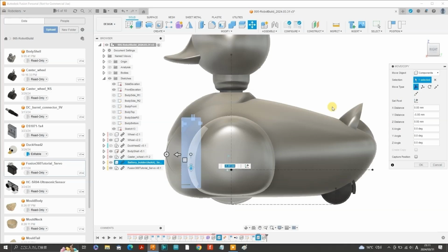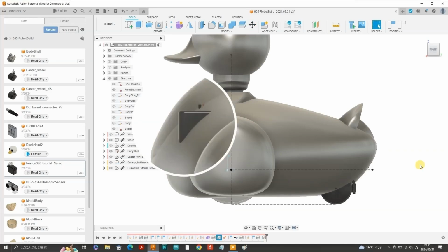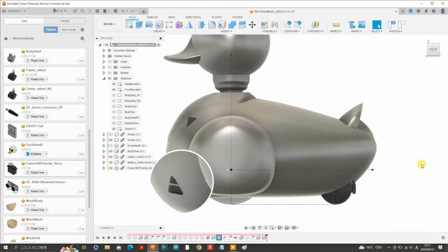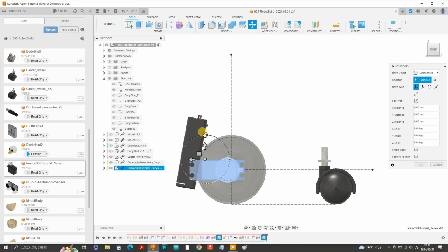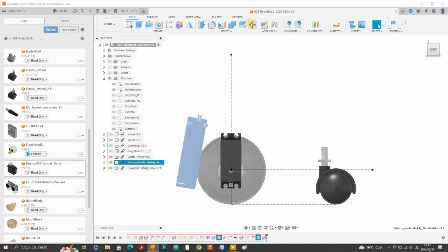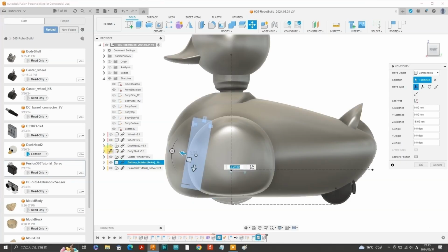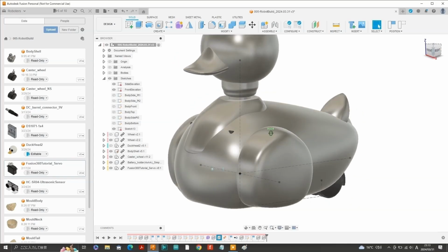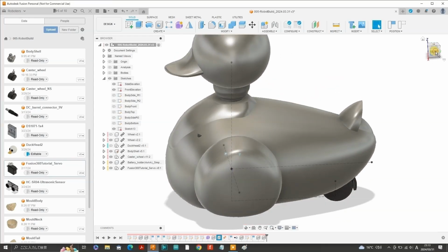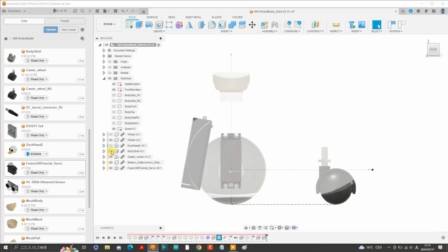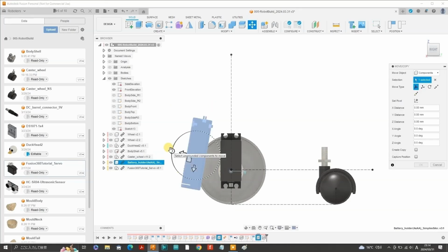If I place the battery holder at an approximately vertical position at the front here, the corners will interfere with the front body shell. So I tried a vertical position for the servo to allow the battery holder to move back more, but 2 of the corners still easily interfere with the body shell here. Also, we'll need to allow for the removal of the battery holder for changing the battery. So I don't think I'll be keeping the battery holder at this position.